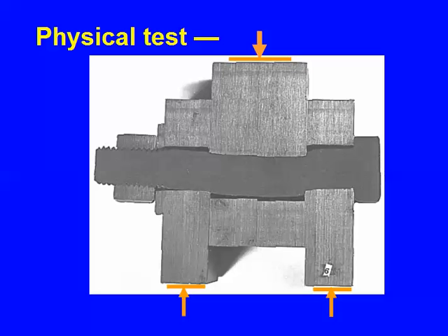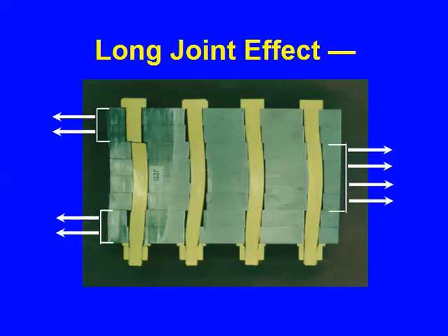Okay, good information. These are the last 4 bolts in a line of, I think it was 13, and 8 inches of grip now. I'm not going to show you the whole picture because they didn't saw the whole joint. So we got the 4 inner plates going to the right and the 2 outer plates, top and bottom, going to the left. And what do we get out of this? Well, quite a lot of bolt bending. That's illustrative.